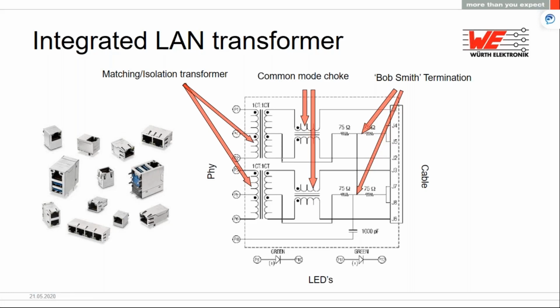Further elements that we can add to an integrated LAN could include something like a triple winded common mode choke and two common mode chokes on one core, which is also referred to as an auto transformer. The reason that these elements are part of some circuits and not present in others entirely depends on what kind of inner wiring you have from the plug to the customer's application. Now, when we have too many lines and too many plug points and there is a lot of crossing, there is some loss of performance. To compensate for this loss, these types of additional elements are needed.